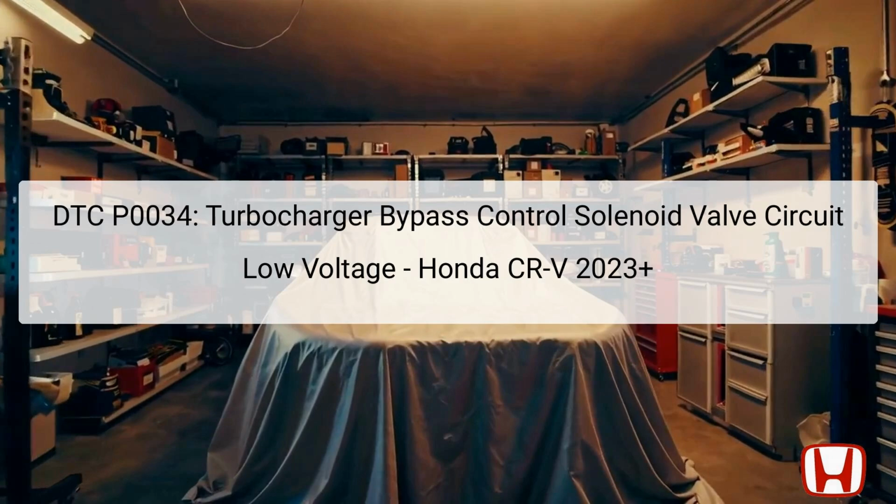DTC P0034 refers to a fault in the turbocharger bypass control solenoid valve circuit, specifically indicating low voltage conditions. This diagnostic trouble code signals that the engine control module, ECM, also known as the powertrain control module, PCM, detects an abnormal relationship between the control signals to the solenoid valve and the actual valve position.